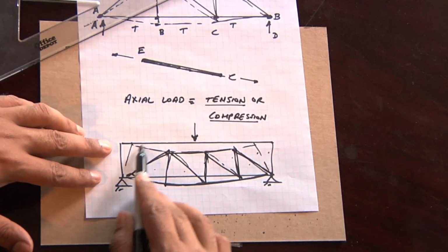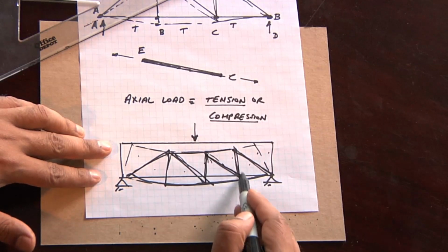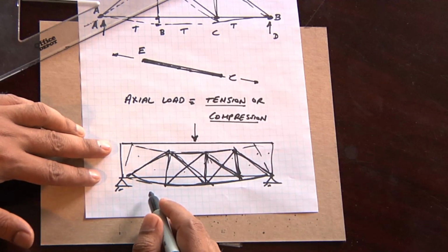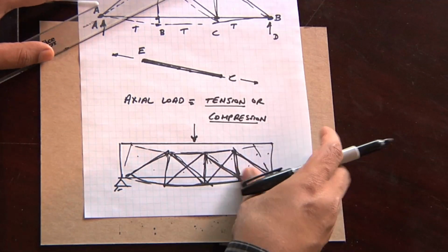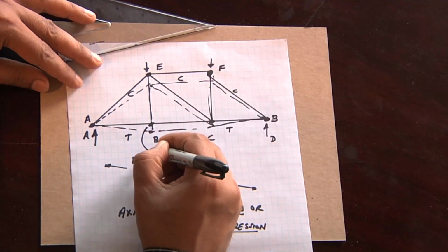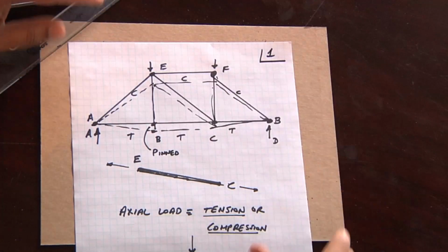In every beam there's an embedded truss where you have diagonal members. In this case we may have double diagonal members. So every joint in a truss is a pinned connection. That means that there is no moment. I'm going to label this sheet as sheet number 1 for module 5. Let's take a look at the next section to understand what we mean by a pinned connection.